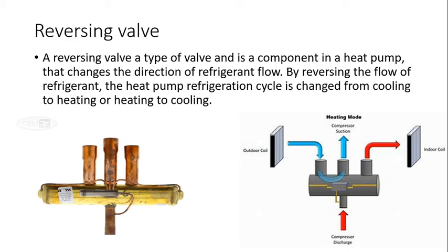I've tried every technique possible. I've bought special tools with long flames on them. It's just very hard to do. They're very difficult to do. And you'll see when you go through the brazing training at school, that unbrazing a pipe and putting another fitting on it is difficult enough, but when you have to do three at the same time, because these pipes are rigid and they don't move, it's not something that's easy to do.